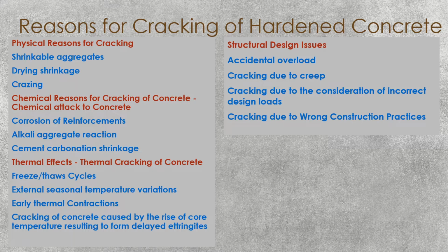Alkali silica reaction is another reason for cracking of the concrete. That's also an effect of the influence of the aggregate in the concrete. Cement carbonation shrinkage is another reason that causes cracking of the concrete. Thermal effects: thermal effects on cracking of concrete, freezing cycles, and external reasons such as temperature variations.